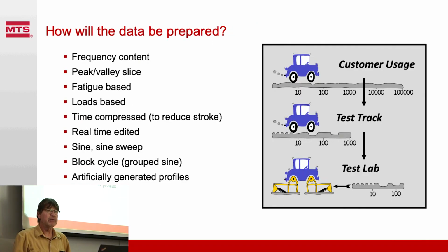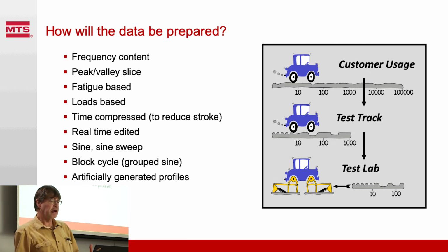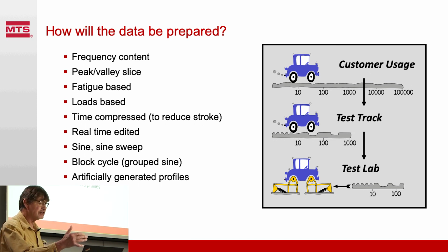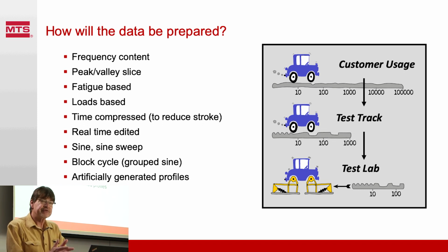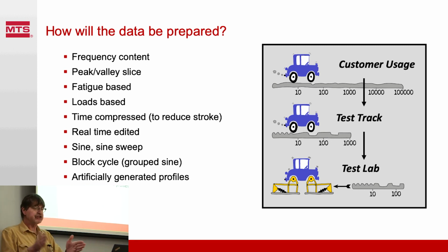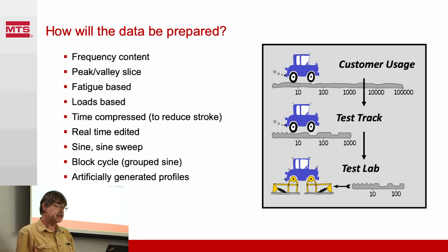The next thing we have to worry about is data. Without good data, carefully analyzed and prepared, we're not going to get a good test. So we should think about how are we going to prepare our data? Are we going to look at frequency content? Are we going to peak valley slice? Is it going to be fatigue-based or loads-based editing? Time compressed, maybe to reduce some stroke or to compress time to make shorter tests. Are we going to take real-time data and just cut some pieces out? Can we do that? Can we paste it all back together and have it still work?